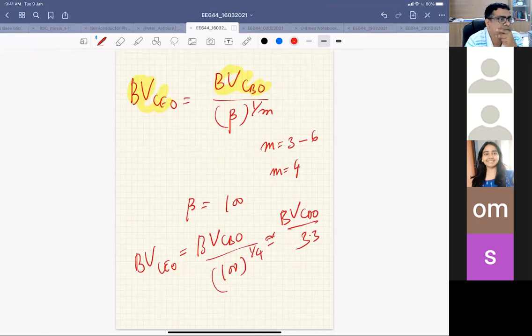Yes, sir. So the question is a bit different. In the power electronics course, we were told that if we have to use a BJT as a switch, we use it in an open base configuration. We connect the circuit across the emitter and collector, and unless we inject current in the base, the BJT does not conduct. So it acts like an open switch, and when we inject current in the base, it works as a closed circuit.